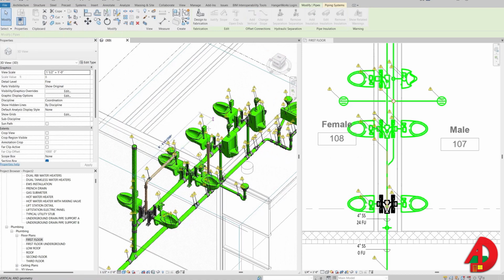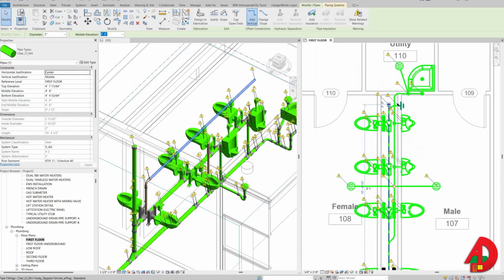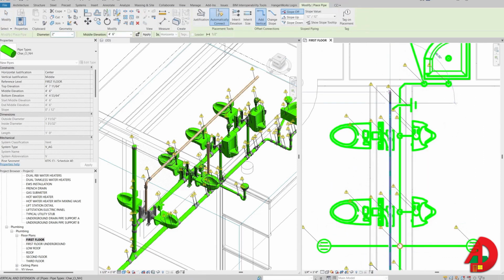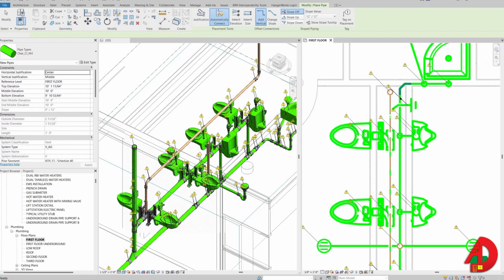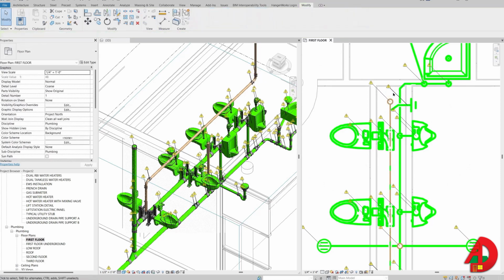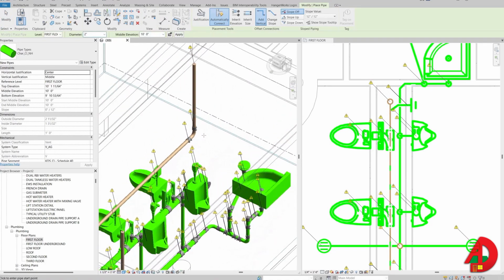In my 3D view, I can just select the open connector of the pipe and extend it holding the shift key to make sure it stays straight. Back to the plan view, I can extend it a little more, and then if I type 10 and click apply, I will model a riser and maybe move it a little using my keyboard arrows. Let me just shift this 3D view because I'm going to focus on this area.